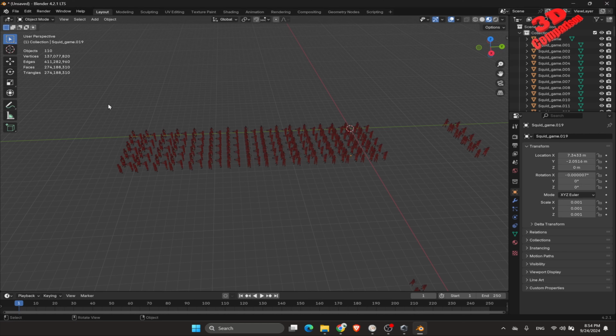But again, keep in mind that you should use those specific techniques. So you should use, for example, Alt-D when you copy this and not Shift-D. And yeah, again, within a large scene, it would be highly recommended to have those sorted into various layers and have them hidden when you are not working with them. And that will optimize the scene. But we see that Blender can process a high amount of triangles.